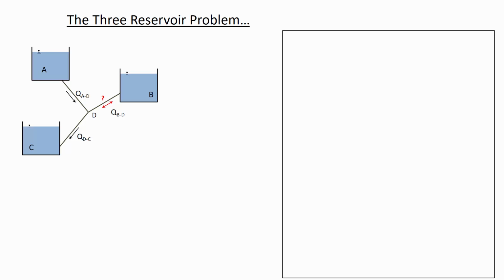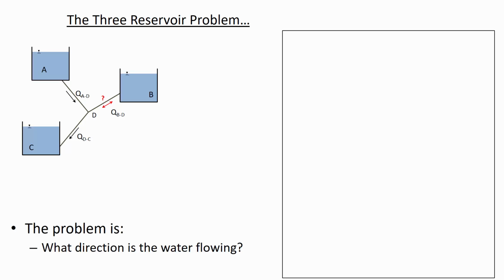So think of what he's saying is, what if pipe DC is so small, the water's not really going to want to go through a small pipe, just because there's a lot of resistance to flow in a small diameter pipe. But what if the pipe to DB was a big diameter pipe, so that there's less resistance? So the water would go into both reservoirs, but it's going to find the preferential path, and it's going to immediately balance the flow rates depending on the resistance. And so the factors that affect resistance are the roughness of the pipe, the diameter of the pipe, and when we're calculating the F value, the velocity affects the roughness of the material F.